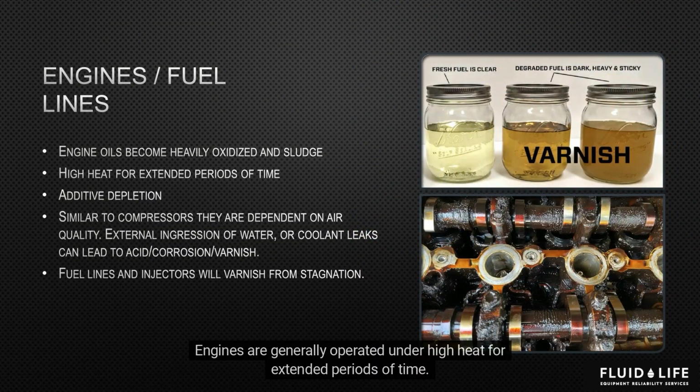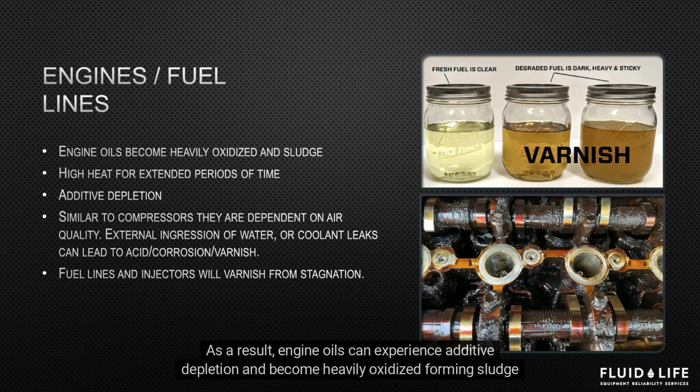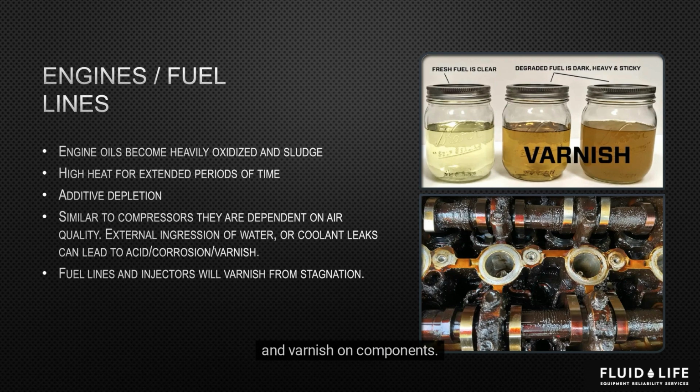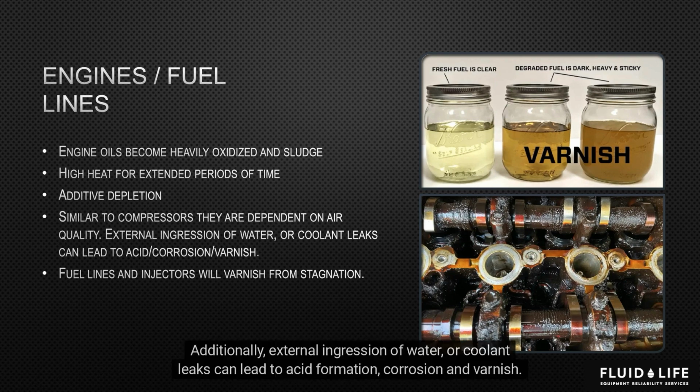Engines are generally operated under high heat for extended periods of time. As a result, engine oils can experience additive depletion and become heavily oxidized, forming sludge and varnish on components. Additionally, external ingression of water or coolant leaks can lead to acid formation, corrosion, and varnish.